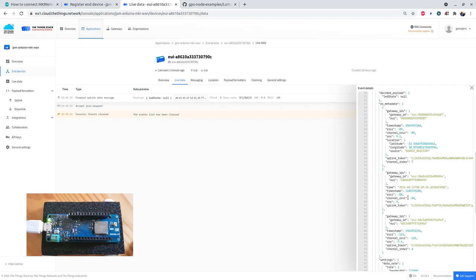The second gateway received me at a slightly higher RSSI value and also a signal to noise ratio of quite high, a 9. The third gateway, however, we see an RSSI of -121, which is the lower limit that we would see, and a signal to noise ratio that is negative. And in this case, it's quite negative. So this gateway, the last one, barely received us. And these two top gateways received us very well. So I've got 2 very good gateways here and a gateway that's not performing well. Because both are negative, I assume this gateway is very far away.